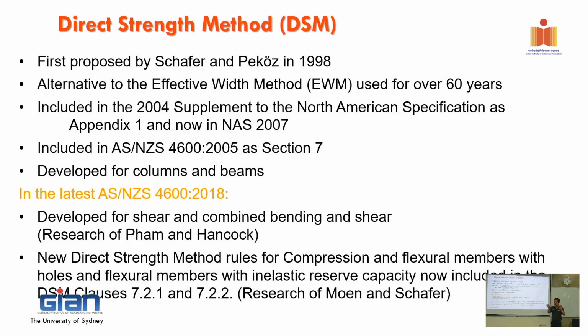Now you can cut holes in the member. So it's very popular, right? Particularly for steel structures, normally you cut a hole in the web to fit all the aircon systems like this one. You're not going to cut into concrete, but for steel it's easy to cut a circular or slotted hole or any shape, and you can reduce the height of the ceiling.